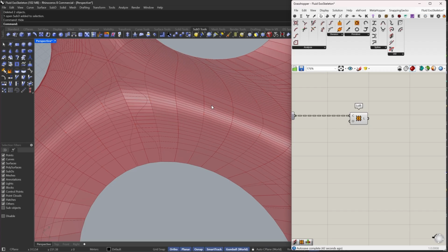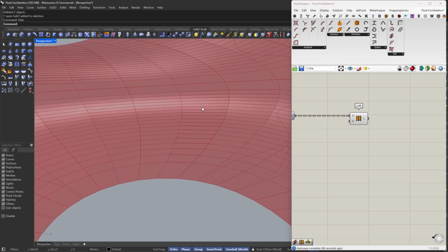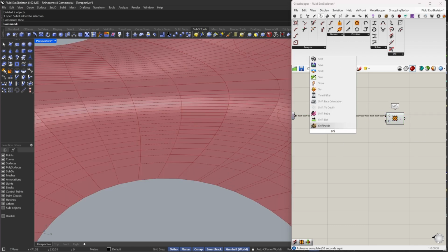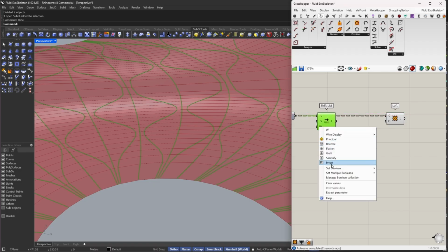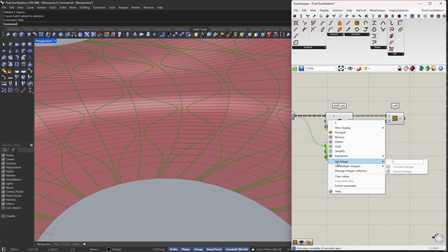And even after changing this to straight, you still have to separate them because these are flat. So in the loft logic, it will make one surface. So in this case, I'm going to shift this and make this invert and graft, and I'm going to copy this, and the first one, I'm going back to the number, I'm going to make it -1.